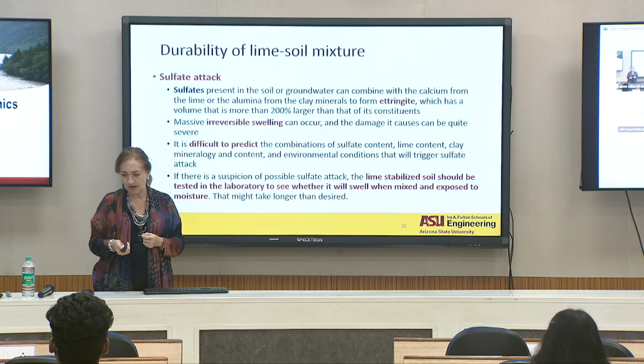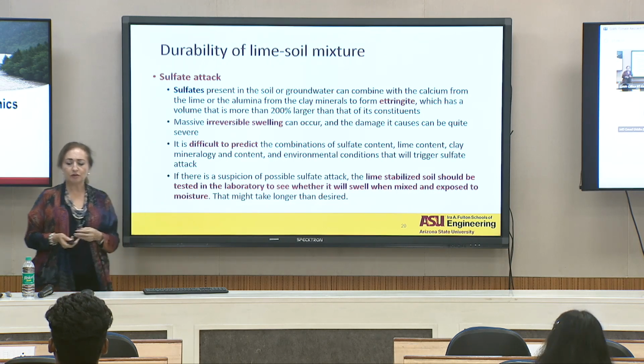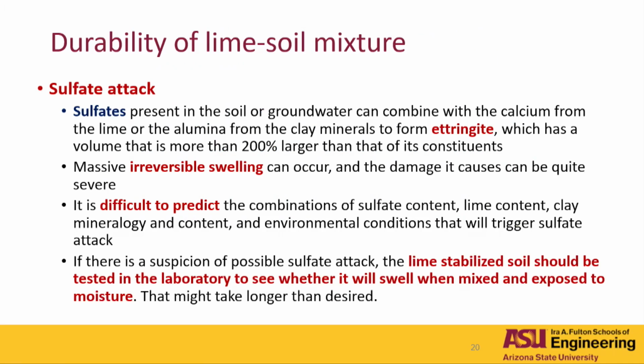So you better take provisions about that. If there is a suspicion of possible sulfate attack, the lime stabilized soil should be tested in the laboratory before that. You need to test for that, basically introducing water into it to make the sulfate soluble and see what's going on, right? There are some tests available for you to make sure that that's not going to be a problem.